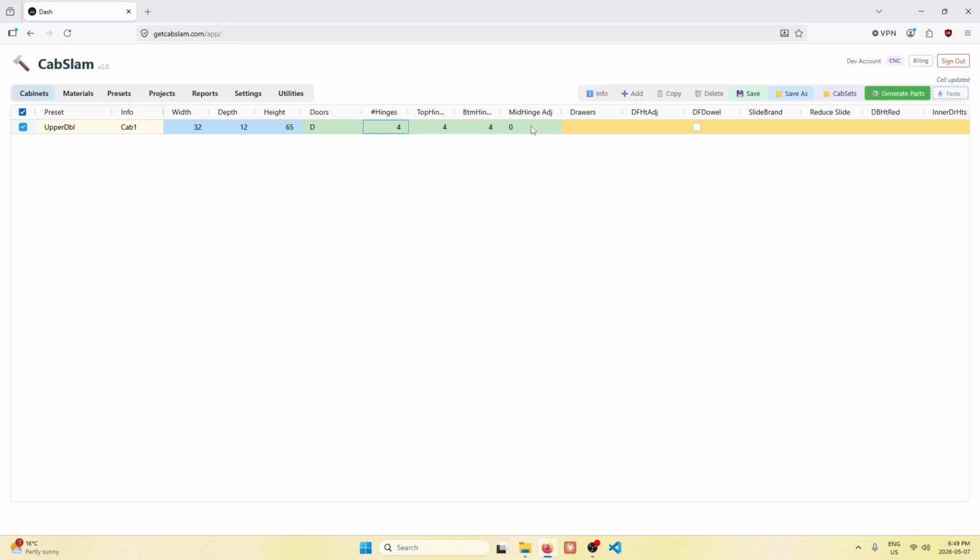That's another video. And so we move over now to the reveals. So we've got 1/16 on the left, 1/16 on the right for the door reveals. We've got 1/8 on the top and -3/4 on the bottom, meaning that that's either a finger pull or it's covering up a light panel. Or you can do both. You could go -1 1/4, which leaves 3/4 for a light panel, and then an extra 1/2 inch as a finger pull. So that's doable. Construction holes are selected with a 9-inch spacing.